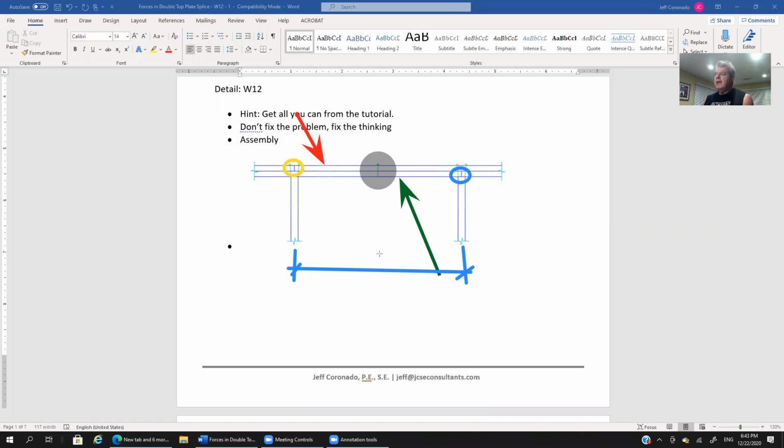That representative nail is the nail that goes between the splice, so it goes from here to here. Whether you specify a nail at a certain distance, might be a 16D nail at 4 inches on center, I think more typically, and this is how we would do it, we would specify the total number of nails that we want in between this splice.